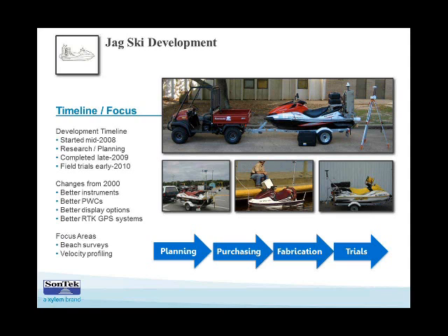So you would monitor, say, pitch and roll. You could actually use your elevation, if you filtered it a little bit, to compensate for heave. And that's actually gotten a lot better. But one of the challenging parts was always referencing your depth measurements to some consistent vertical datum.